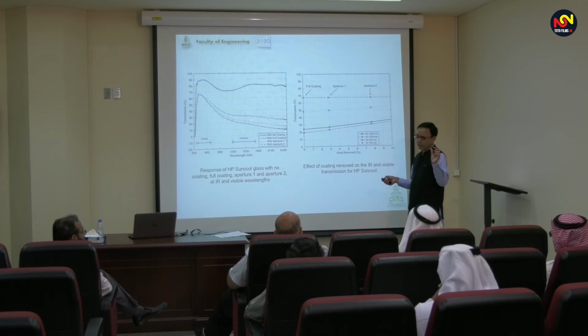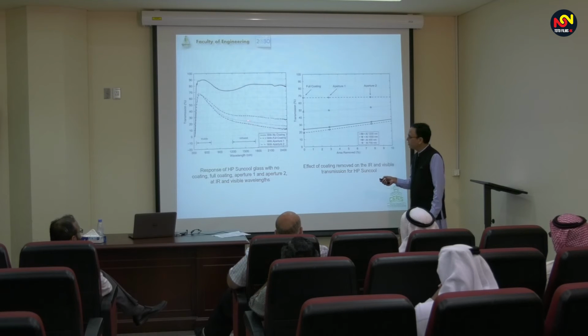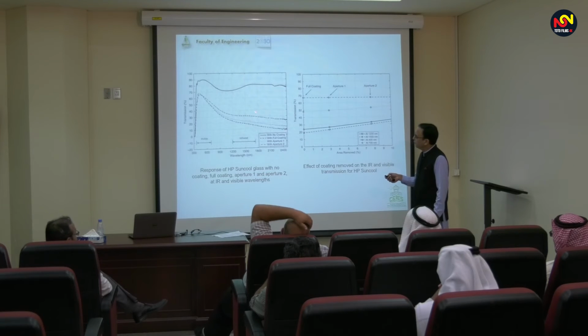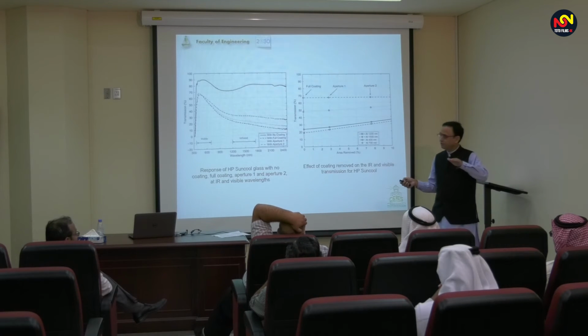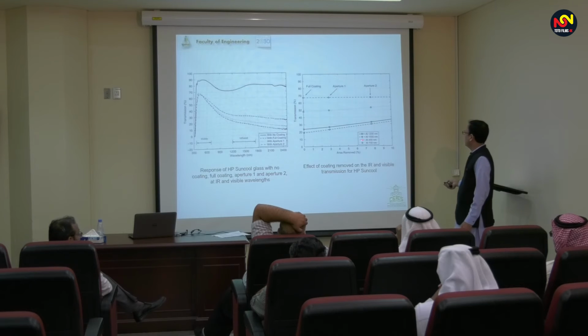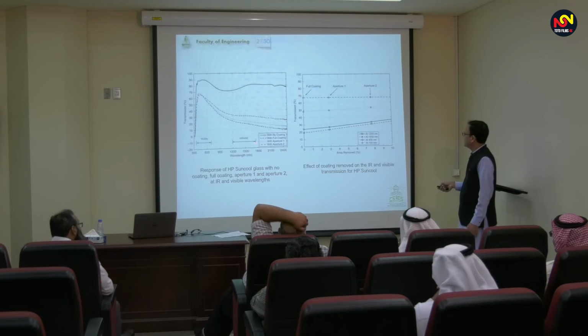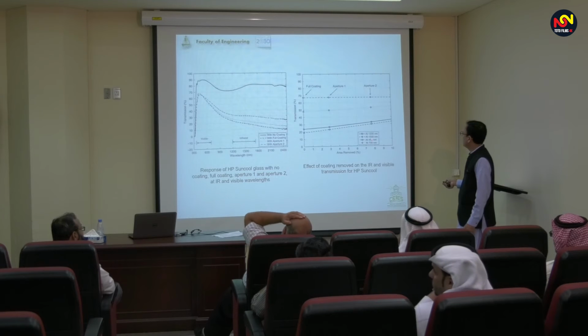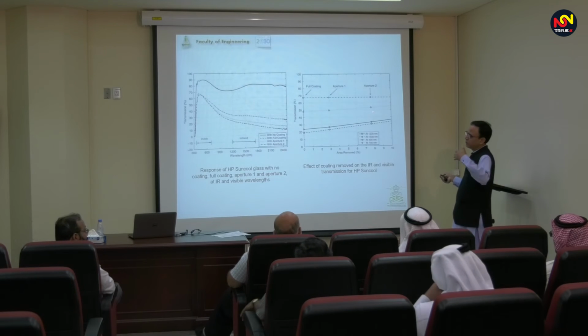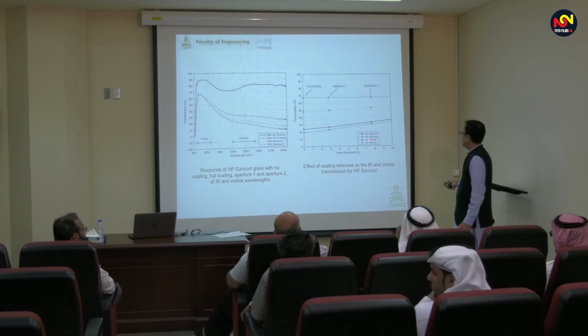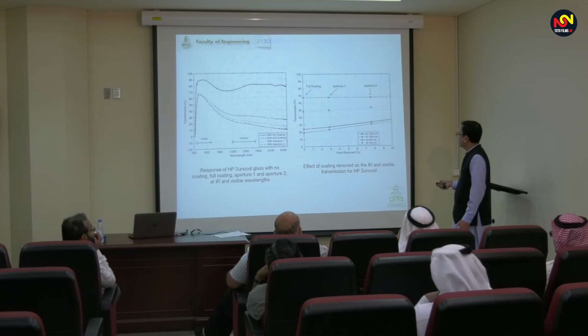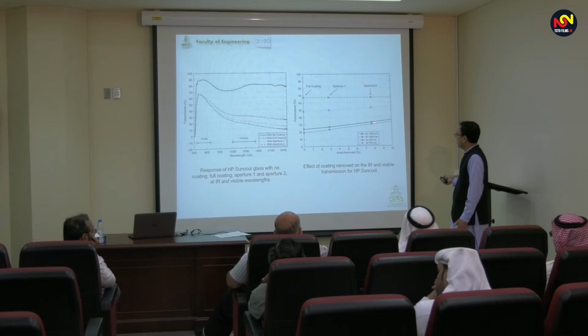Now when I take a small area out, there is a heat loss here, because it was giving us about 80% and now it is giving me maybe about 78 or 77%. So there is a loss here. Then if you go here, when I took another area out, the efficiency is going down and down and down. And when I plot it, you can see at these wavelengths, 700 and 400, there is no change, because it's glass, so there will not be any problem with viewing. But if you look at the infrared where the heat is, the percentage removed is actually linear.